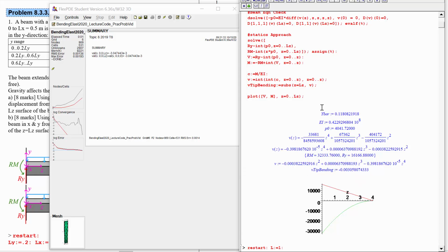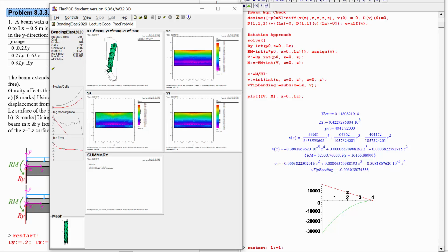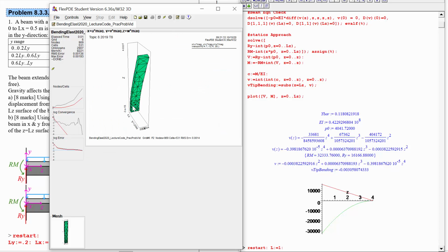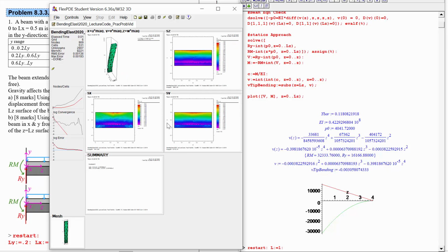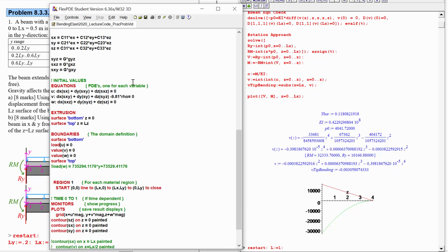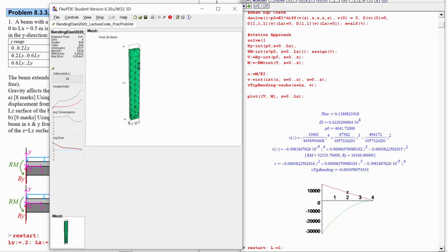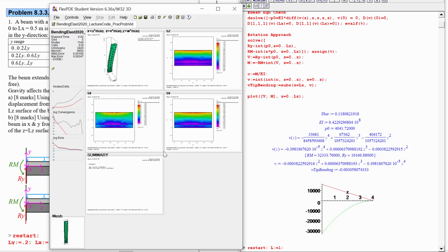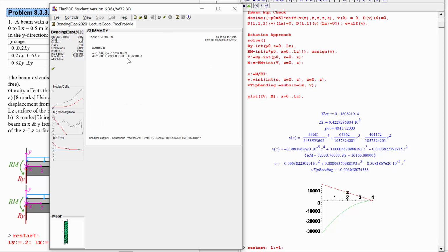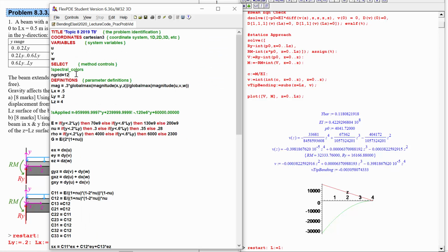What about the shear deformation? So that would actually make things slightly worse. We still have a bit of coupling of stress in the vertical direction, making it a little bit stiffer at the wall than we would like it to be. We could try increasing the grid density, forcing it to try to use more elements, and see if that makes a difference.